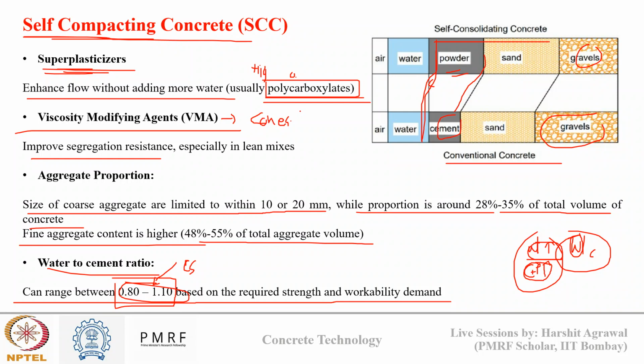Is there any specific kind of superplasticizer? There are a lot of high range water reducing admixtures present in the market. There is third generation, polycarboxylate based superplasticizers. Generally we use this PC type, third gen PC, and there are many more; that detail you can see. There are different generations of superplasticizer: first generation, second generation, third generation, fourth generation. Generally the third and fourth generation we use, and we say that these are high range water reducing admixtures.